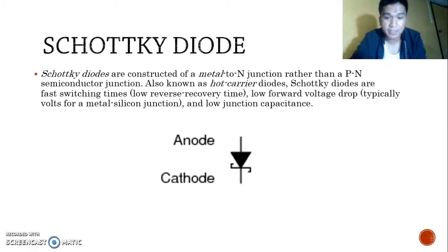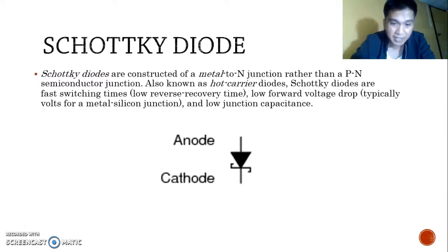Regardless of switching speed, the 0.7 volts forward voltage drop of silicon diodes causes poor efficiency in low voltage supplies. This is not a problem in, say, a 10 volt supply, but in a 1 volt supply the 0.7 volt drop is a substantial portion of the output. One solution is to use a Schottky power diode, which has a lower forward drop.